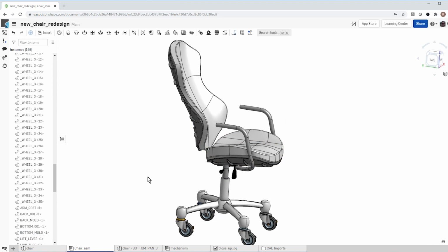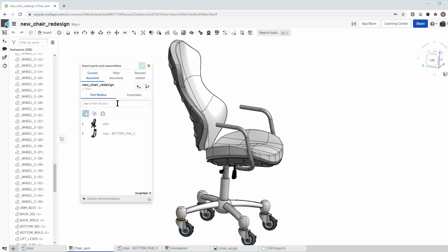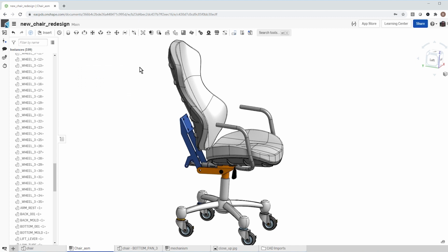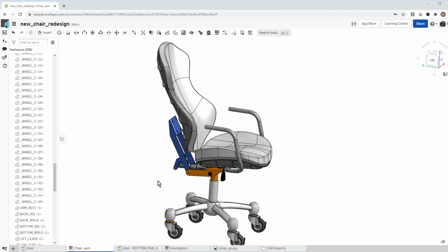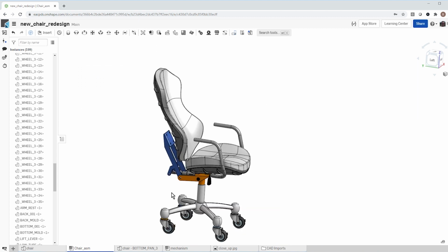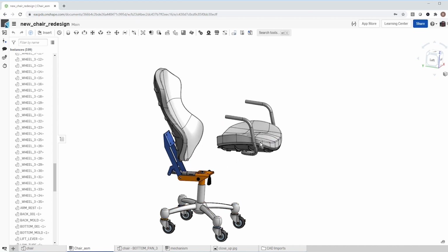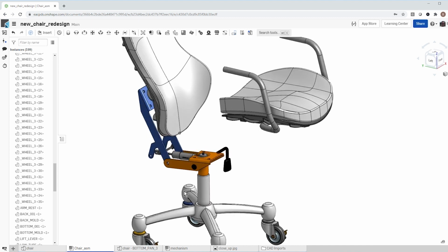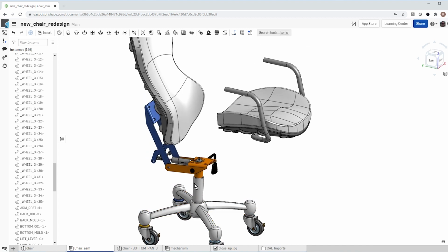So he's gone. And now I can assemble in the part that I made, or the parts that I made. So I'm just going to say, let's insert. It's an assembly, and this is the guy. And because it was using the old part, the way it was oriented, at least comes in the right location, which is nice. So he's just placed there. He's not intelligently assembled. Let's take this and move that. So I could leave it here and it's in the right position, but I want to put it in here